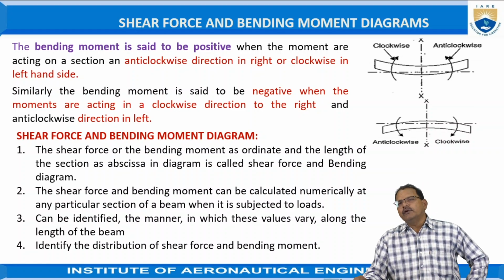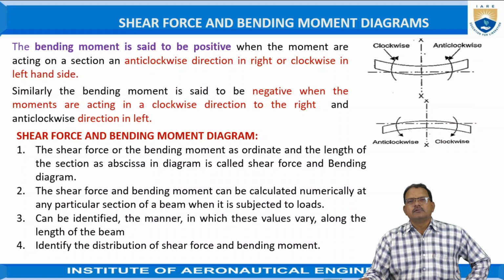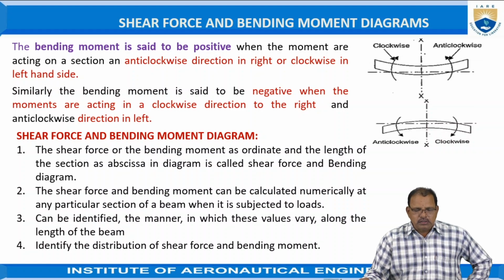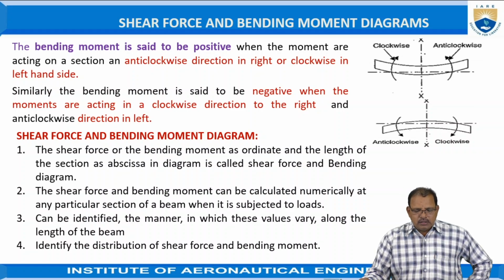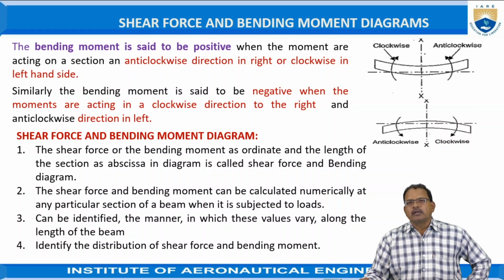If you draw a diagram showing the shear forces acting on the beam along its entire length, that diagram is known as a shear force diagram. Similarly, if the bending moment acting on the object at various positions along its entire length is represented, that diagram is known as a bending moment diagram. Bending moment diagrams and shear force diagrams are most important for the design of machine members.